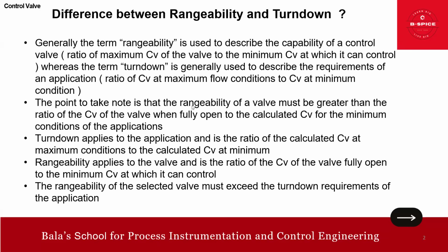So the point to note is that rangeability of the valve must be greater than the ratio of the CV of the valve when fully open to the calculated CV for the minimum conditions of the application. You got it, friends? I will also explain that in a better way in the next slide. You will understand even more.